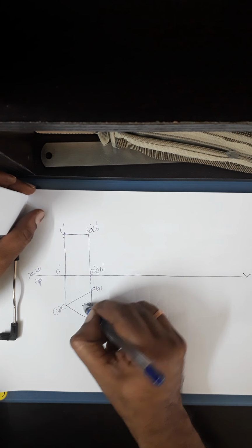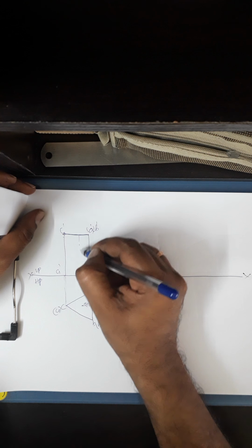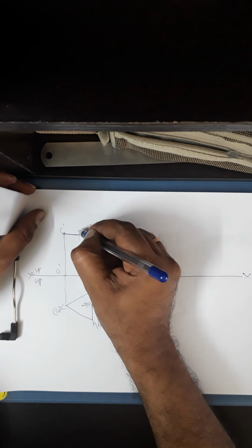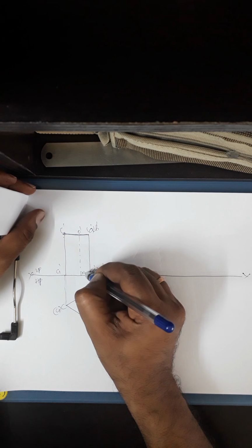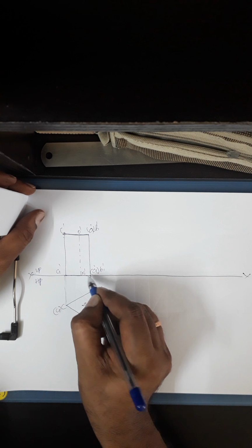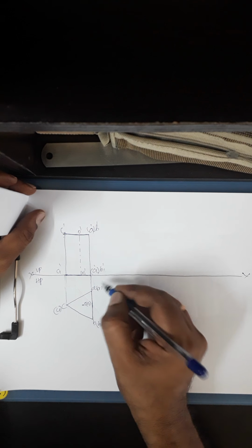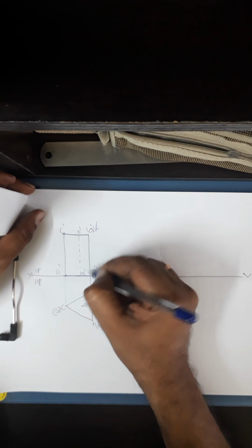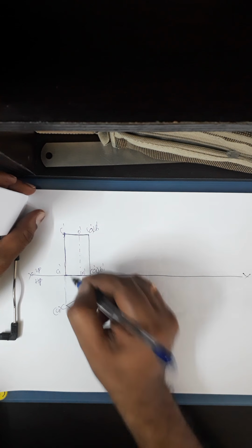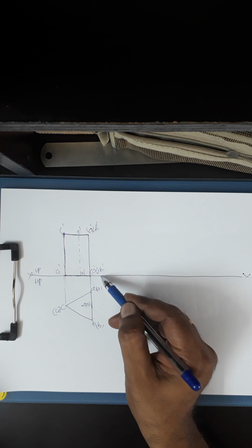So this is the axis, so I can represent the axis using a chain line: a big dash, a small dash, big dash, a small dash, big dash, a small dash. So O dash, O1 dash. And this is the base, right? Okay. So that should have a thick line compared to this. The XY line should be drawn using an H pencil, whereas I should differentiate the base from the XY line, right? So it should be dark compared to this XY line.